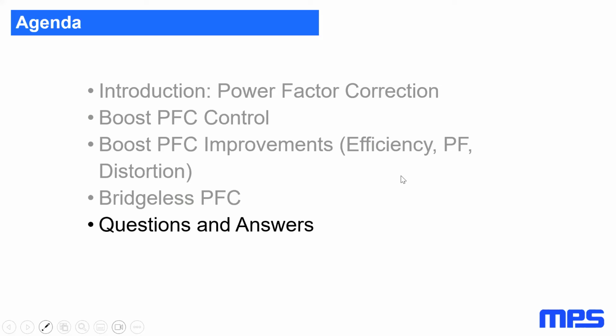Of course, the MOSFETs are usually external, for the reason that at this high power we want to spread the heat and not have everything in one spot. So the MOSFETs are external, but the control is one common controller for both stages, the PFC and the DC-DC. So yeah, this exists. HR12XX family, we have many parts like this.